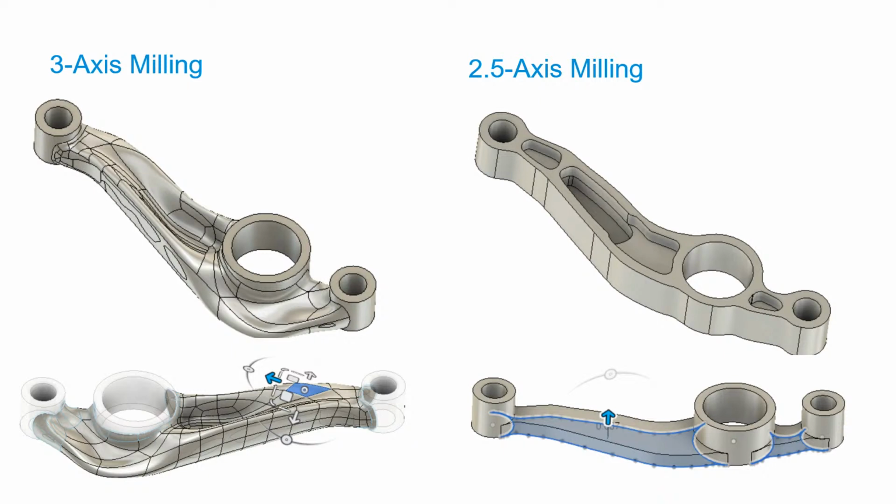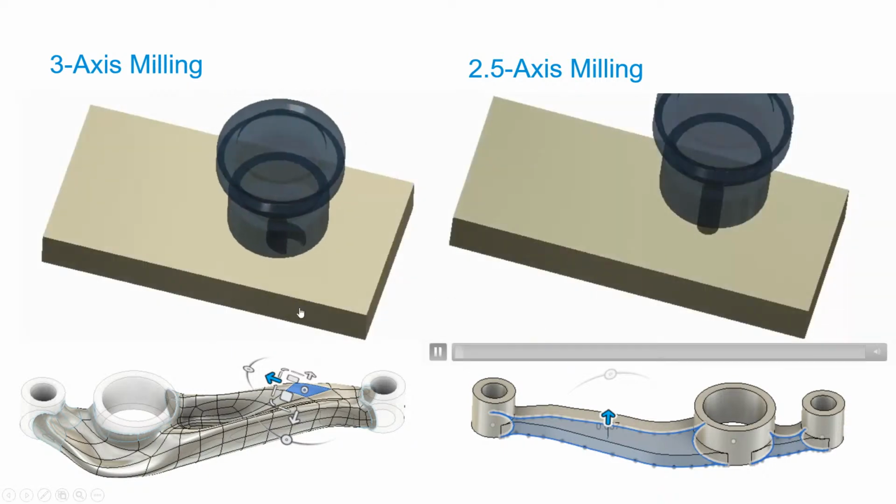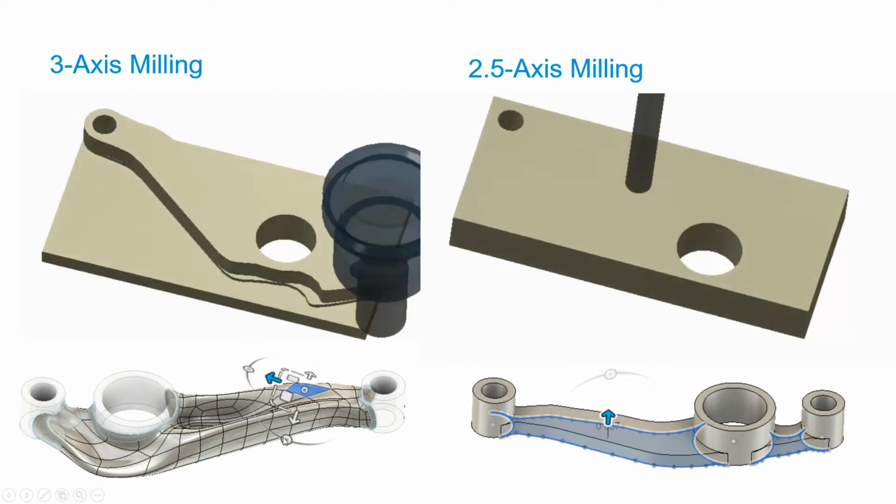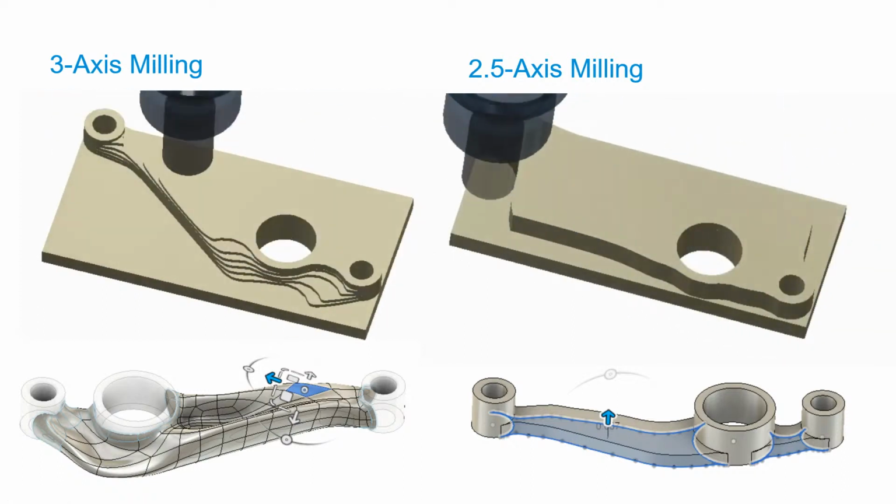But to really understand the importance of each one, you can look at it even just looking at the CNC options. So within generative design for this project, we set up a 3-axis milling operation and a 2.5-axis milling operation. But the major advantage of looking at all of these is that the result that you get from generative is going to be very unique for each one.